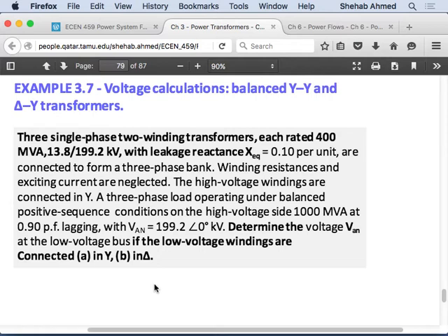So delta-star-delta does not matter. It's the equivalent impedance in per unit. As long as the impedance is in per unit, and you're going to derive your per unit equivalent circuit, and you are properly going to choose your bases such that the ratio of the bases is equal to the ratio of the terminal voltages of the transformer, then even if they tell you star-star, delta-delta, star-delta, I don't care. The X does not change because it's in per unit. Not like the previous problem where I divided by 3 because I drew the single-phase equivalent circuit in real quantities, not per unit.